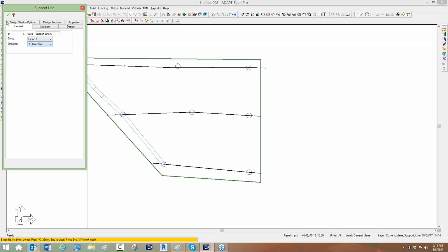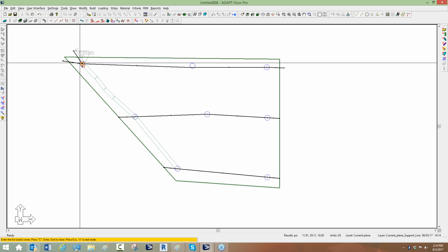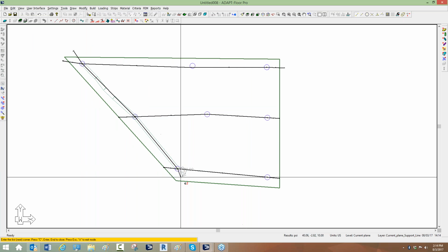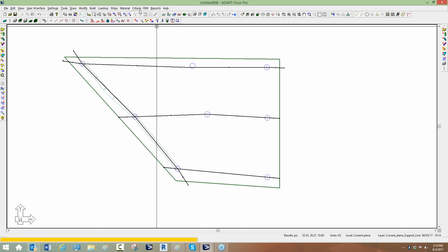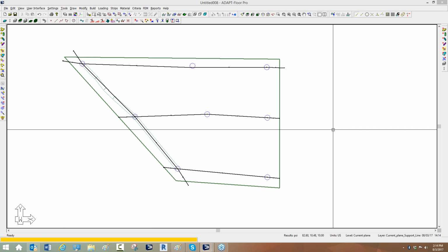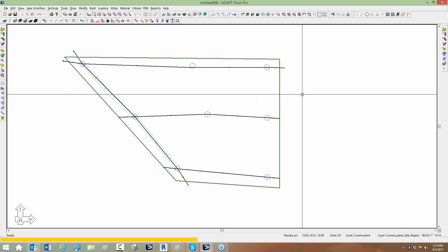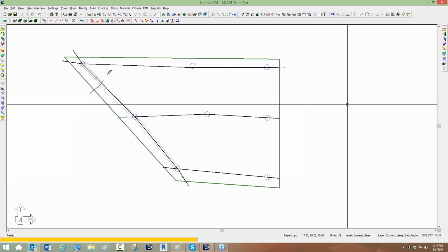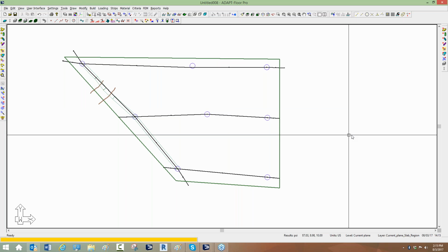the X or in the Y direction, if I go and click on that point, and I have that regular floor system selected in criteria under my analysis options, what's going to happen is the section cuts that are within this segment and this segment, those cuts will not include the beam stem because their endpoints are not clicked on. So that was my comment related to segmenting beams, and that can completely be bypassed if you use the option for waffle joist construction. So hopefully that clarifies.